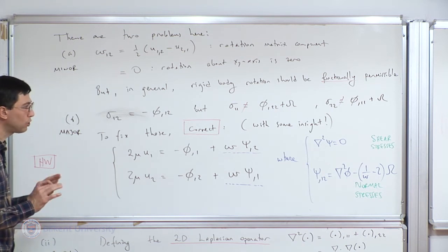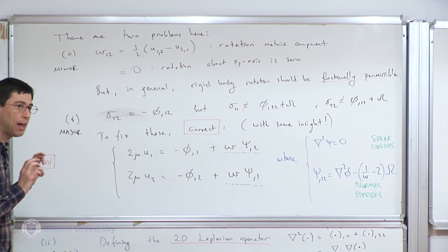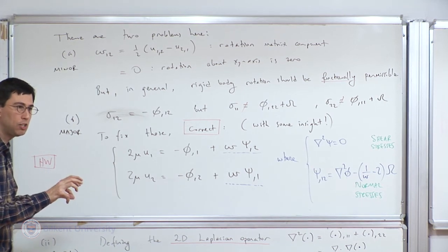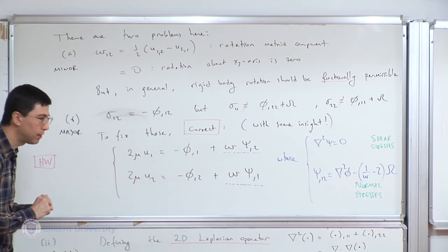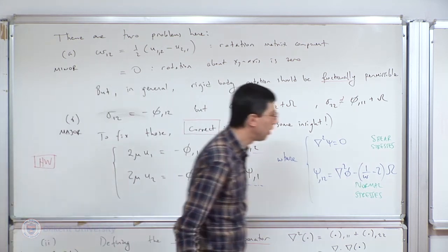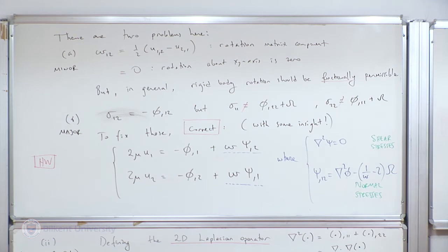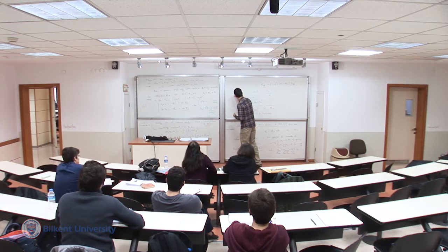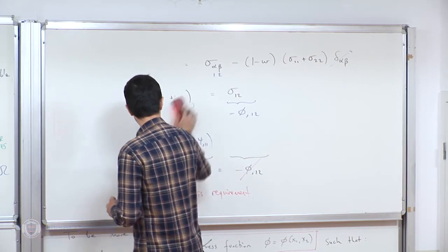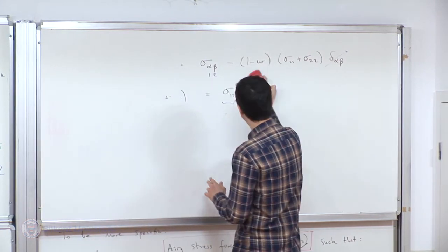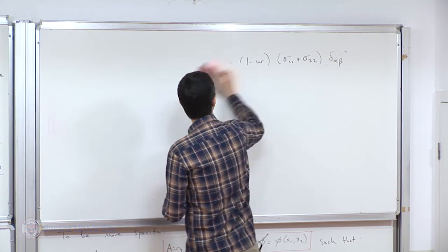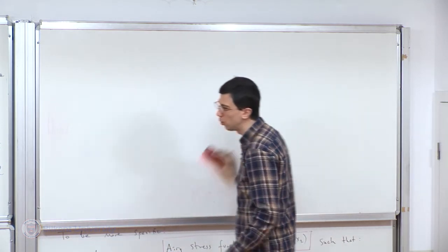So now for a specific problem, I need to go, and the very first step is to pick an Airy stress function. Now, I'd like to very quickly give you a perhaps too trivial demonstration of the fundamental aspect associated with the Airy stress function. In other words, often, not always, we will choose the Airy stress function to be some polynomial.